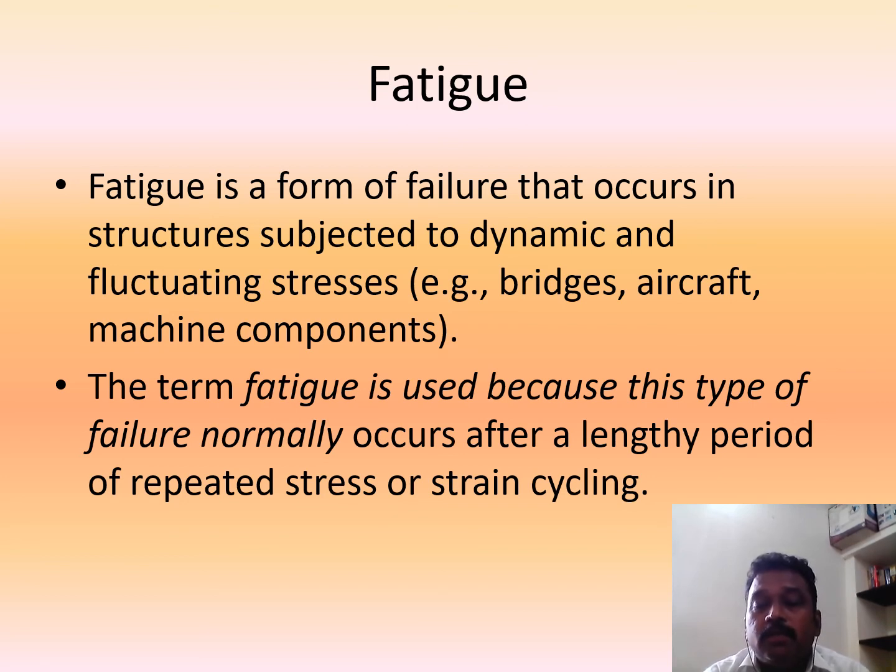In bridges, whenever the traffic is there, when a vehicle moves over the bridge, only then does the load act. Otherwise, no load acts on the bridge. Similarly, in an aircraft, only when it is flying is the load acting on the wings. Similarly, whenever the machine components are kept in use, the load acts on the component. The term fatigue is used because this type of failure normally occurs after a lengthy period of repeated stress or strain cycling. After a long time only you get that failure.